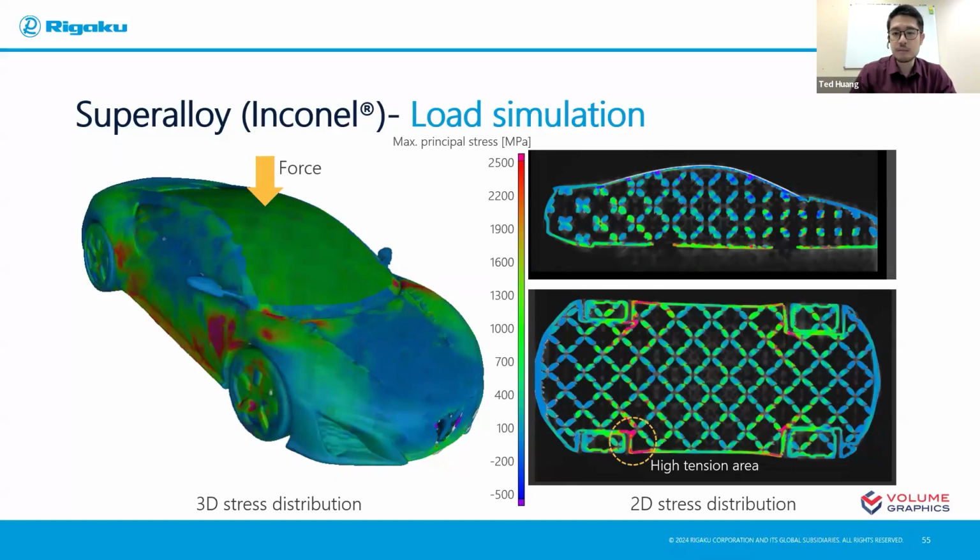So in this case, you can immediately answer a question like, is this surpassing the material property of the Inconel? Well, in this case, obviously it didn't. But with this, you will be able to modify the product, maybe increase the thickness, maybe change the distribution of the struts inside, and then you can move on to your next iteration that improves your additive manufacturing product.